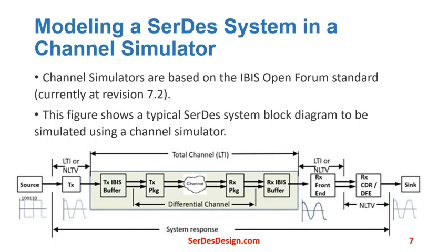Modeling SerDes systems in a channel simulator. Channel simulators are based on the IBIS Open Forum Standard, currently at revision 7.2. This figure shows a typical SerDes system block diagram to be simulated using a channel simulator. This block diagram is generic for any channel simulator, but each tool has its specific way to represent this block diagram. The constituent parts of this SerDes system include the following: transmit IBIS-AMI portions.